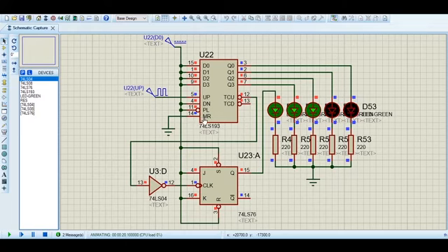The clear or reset input is attached to the ground as seen here, which means it is not triggered in this circuit. The up pin of this chip is attached to a clock generator, and the DN pin is attached to a 1 input, so therefore this counter would count up. The JK flip-flop here is configured as a T flip-flop as shown here, with the inputs J and K connected to a 1 input signal.